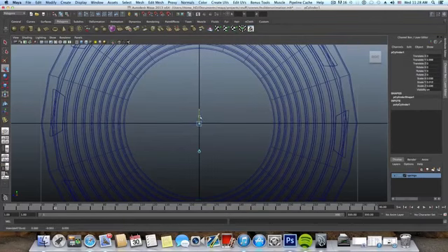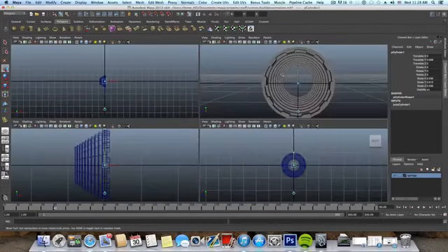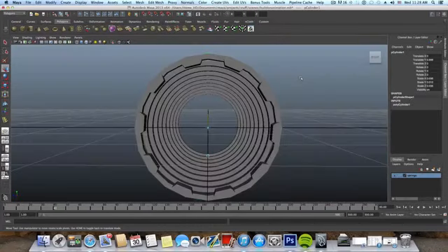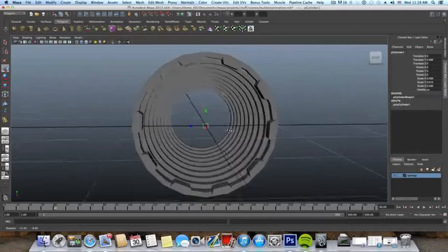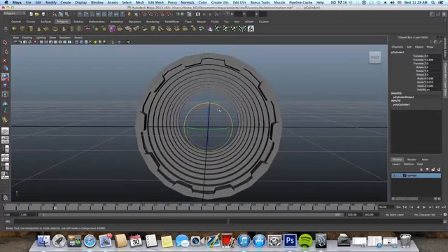Tap spacebar, put your mouse cursor over here, spacebar again, and when you're done adjusting this, tap Home or Insert again, depending on your operating system. After you've done so, switch to the rotation tool, and grab this spring here, the red one.